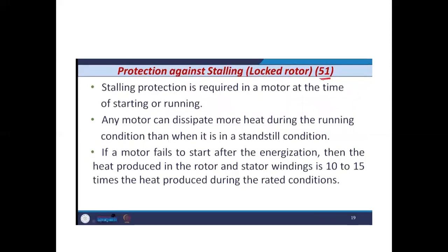Now we have to discuss the protection against stalling or locked rotor. The stalling protection is required in a motor at the time of starting or running. Any motor can dissipate more heat during the running condition than when it is in standstill condition. So if the motor fails to start after energizing, then the heat produced in the rotor and stator winding is 10 to 15 times the heat produced during the rated condition.